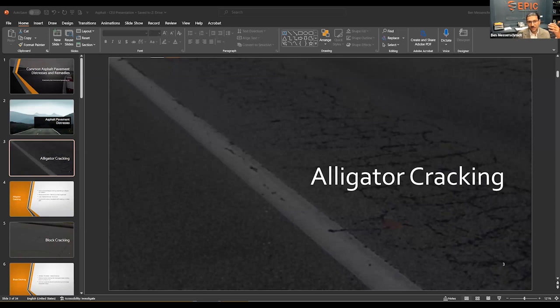It's going to give you an idea of why this may be caused and whether or not you have items underneath that may be reflecting through. And you see some of the common causes for block cracking is going to be over hardening or shrinkage of that asphalt surface. So the shrinkage is going to be during the curing process. Now, if that shrinking cycle occurs too rapidly or too slowly, it's obviously going to cause some internalized stresses that may present themselves on the actual surface. Same thing goes for a lot of cementitious based materials as well. That curing process is really going to be crucial on the overall performance and at least visual aesthetic to the system.